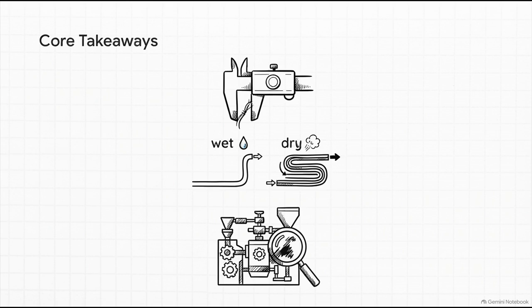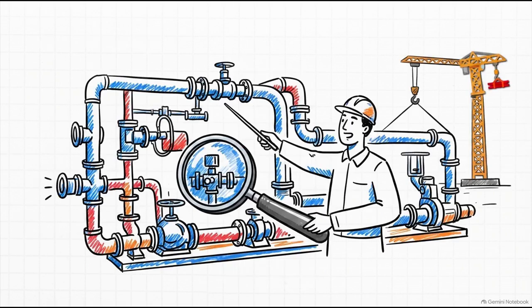Number 2, understand the fundamental air requirement differences. Wet mix requires way less air than dry mix simply because the pump is doing the heavy lifting. And number 3, you absolutely must evaluate the equipment and the mixture as a single, connected, living system. Which leads perfectly into your main field takeaway for today.